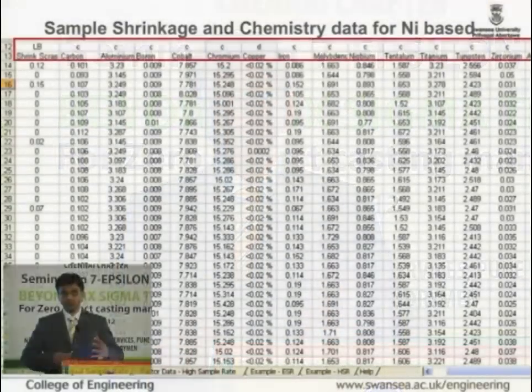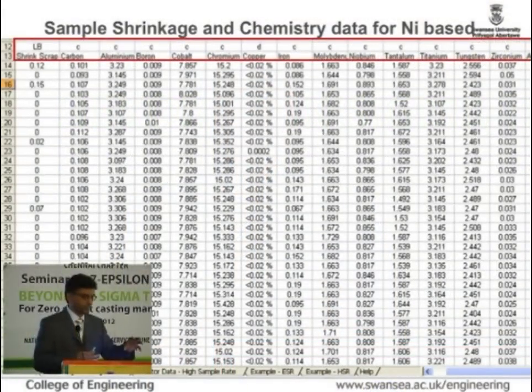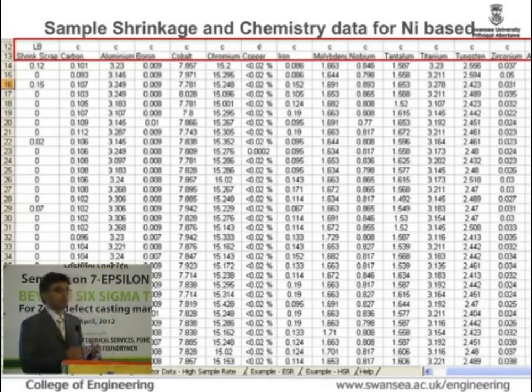Various turbine blade manufacturing companies don't have the same composition, although they make the same alloys. And that is applicable for any foundry. Your chemical compositions for the same alloy would be similar. The trends are valid, but the exact values, the actionable information, are different. That's why if you just take one change from another foundry, it would not apply to your situation. You need to look at everything that goes into the pot.